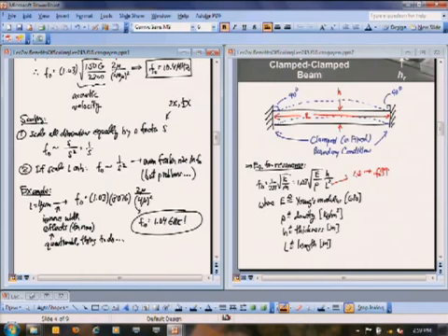Yes? So what's the benefit of the increase to gigahertz instead of 10? A gigahertz is where most wireless is. So your phone, for example, if you have a CDMA phone, it's either working at 900 megahertz or it's working at 1.9 gigahertz, somewhere around there, right? PCS, that sort of thing. GSM is at, what is it, 1.8 gigahertz, right? And 900 megahertz. And so these are the frequencies that cell phones operate at. That's why you want resonators that can operate at those frequencies and select those frequencies.